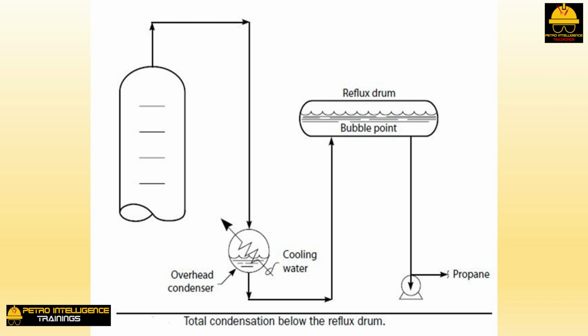But then the liquid in the condenser would be below the reflux drum. How, then, does the liquid get from the lower elevation of the condenser to the higher elevation in the reflux drum? We will have to explain this hydraulic problem later. But for now, we can say that most reflux drums are elevated 20 or 30 feet above grade to provide net positive suction head, NPSH, for the reflux pump. Also, most shell and tube condensers are located at grade for easier maintenance during unit turnarounds.